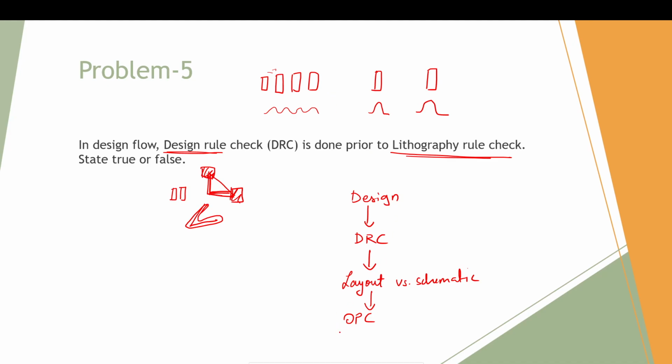That is done at the optical proximity correction, and after this we need to check the lithography rule check. These two basically go hand in hand. Because the layout might have such structures, we do an optical proximity correction, and after that you might put some dummy fill portions in the areas which are sparsely populated, just so that the density of population remains constant overall.